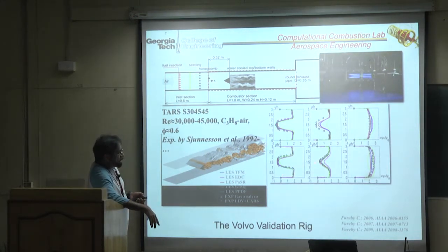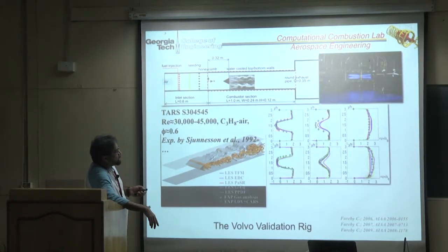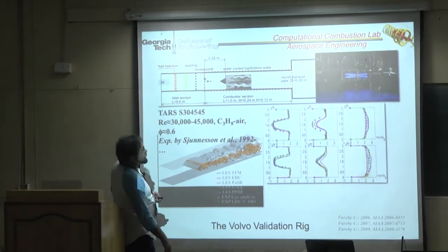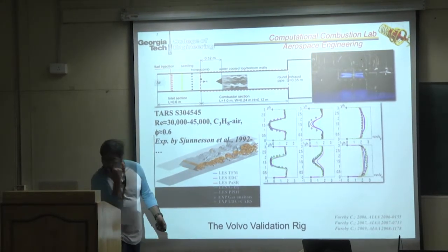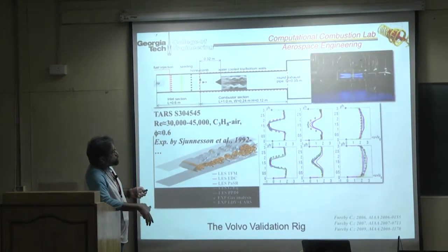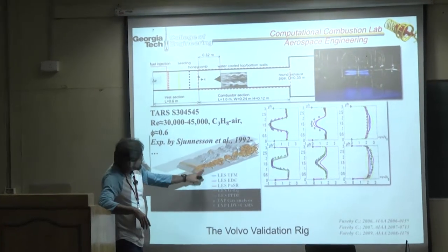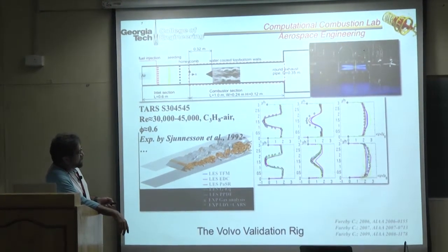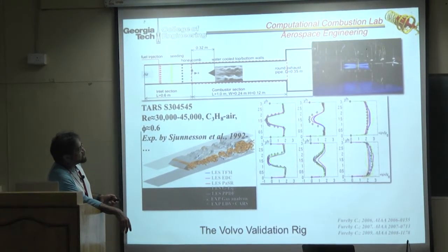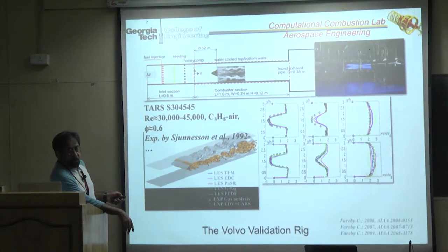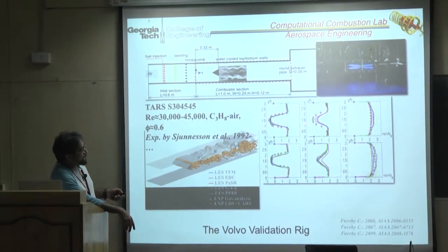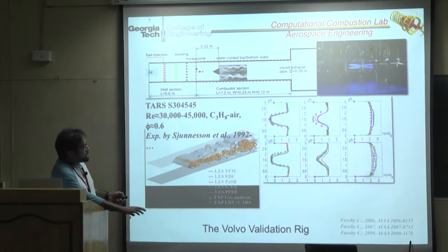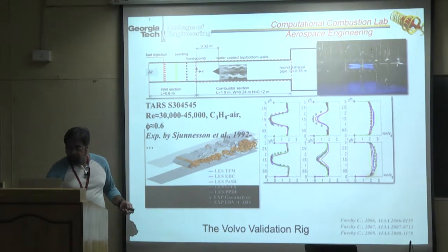But what I wanted to point out is two things. One, that the models, in the average sense, at different locations, you get the mean shear layer. So basically, these are profiles measured downstream, and you can see that some models are not very good. Like the G equation is the green line, and you can see in some places it is way off predicting the result. The partially stirred reactor is overall consistent in this problem. But on the average they all look the same.